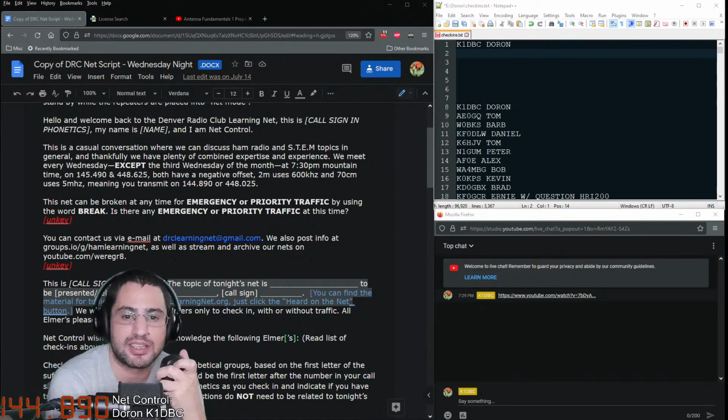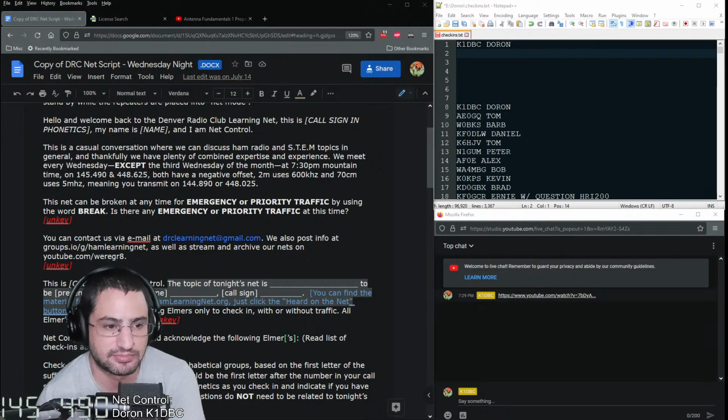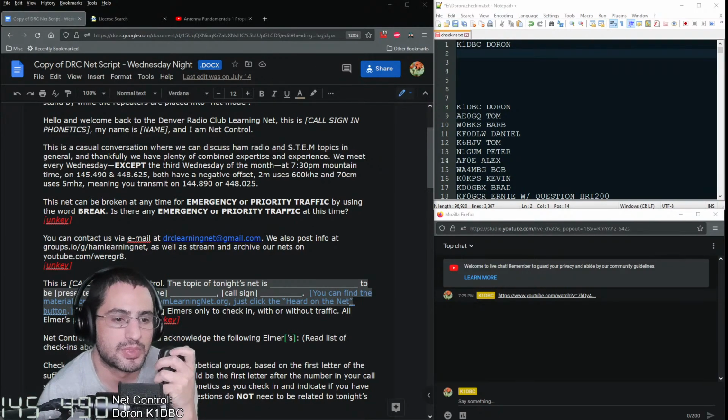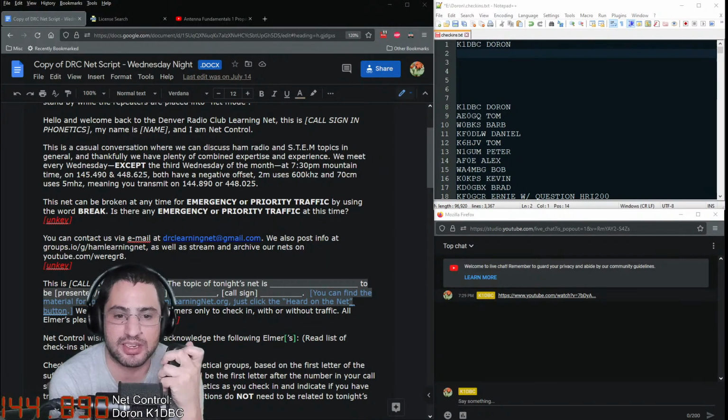We meet every Wednesday, except the third Wednesday of the month, at 7:30 p.m. Mountain Time on 145.490 and 448.625. Both have a negative offset. 2 meter uses 600 kHz and 70 centimeter uses 5 MHz, meaning you transmit on 144.890 or 448.025 respectively. This net can be broken at any time for emergency or priority traffic by using the word break. Is there any emergency or priority traffic at this time?